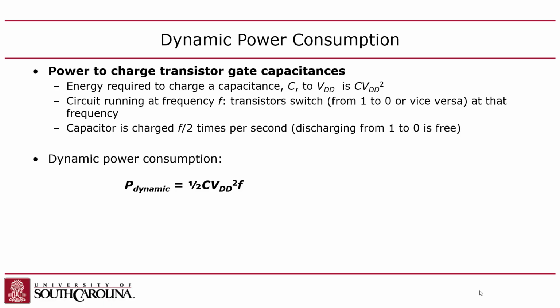So what that was called was Dennard scaling. If you've ever heard that term, Dennard scaling. Dennard scaling meant that if the transistors were shrinking at the same rate that I was adding more transistors, then my power density would remain constant, which means I could go from 1 million transistors to 1 billion transistors and still have the same power density in terms of watts per area, right? So that was awesome, right? That basically meant I could create bigger chips without using more power.